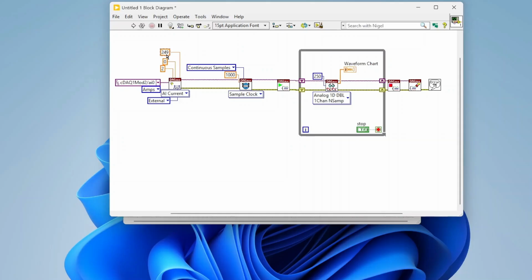Now, if we're doing a larger current range, like for example, the NI9227 goes to 5 ARMS, we might want to use a different value. And again, 1 ohm is a really good value just because it makes math real easy. But again, DAQmx is doing this for us, so who cares what value we use, as long as it works for your circuit. So that's really all we need to change for method 2. We need to specify what our range is, right? Our min, our max. We need to specify the external shunt, and we need to make sure that we have defined that this is an external shunt.